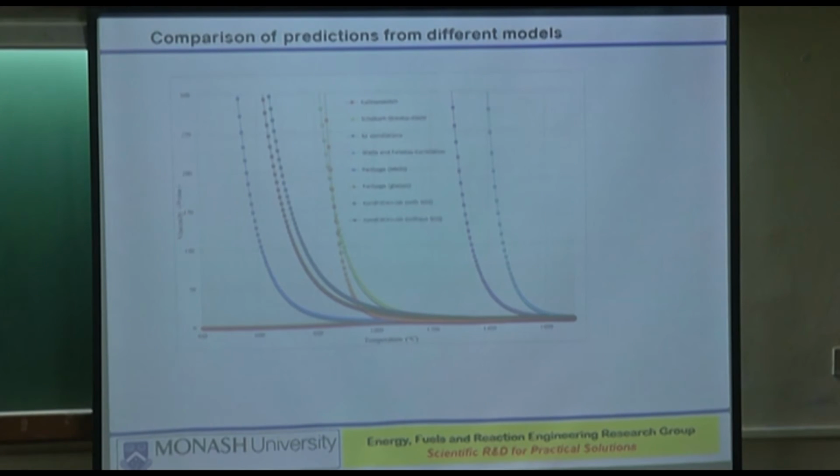The other gases in a gasifier are carbon monoxide and hydrogen, but I cannot put carbon monoxide and hydrogen inside that environment without looking at their lower and upper flammability limits, because no safety committee will permit you.